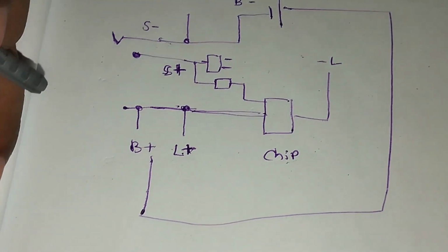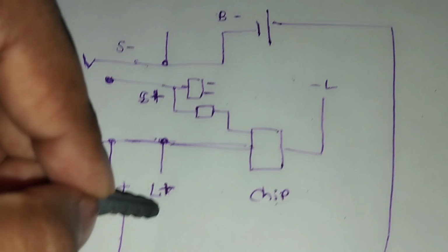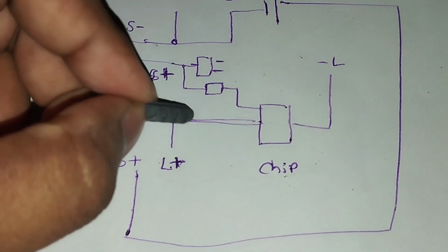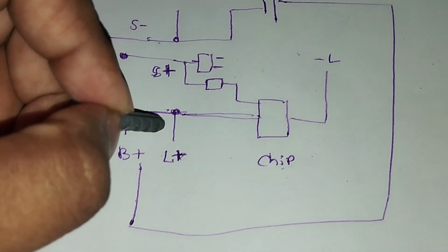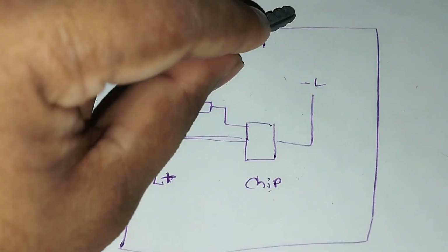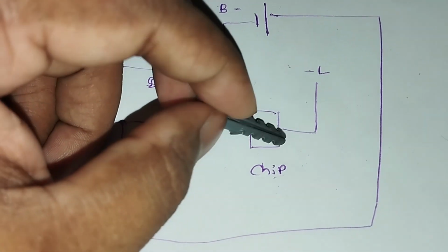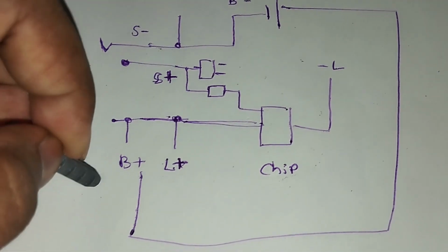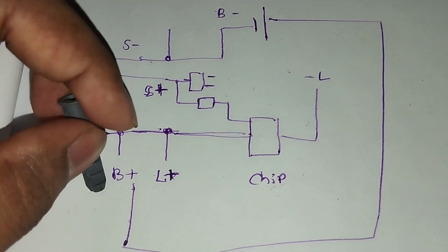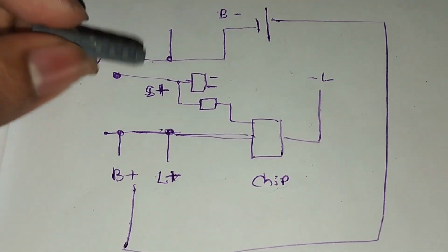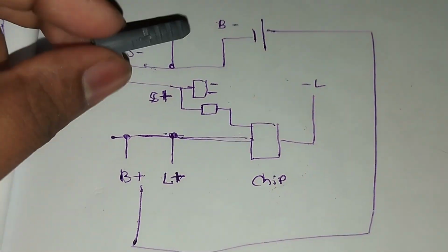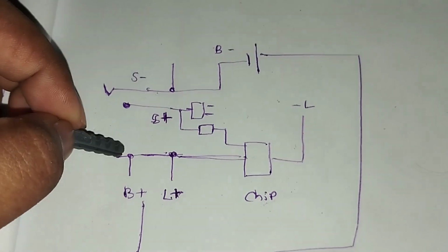Then they have supply negative also traced directly to the battery. That doesn't ensure your supply voltage is correct, or the correct polarity, or that plus and minus aren't mismatched. This plus goes straight to the transistor, but even if there is a misfire, it gets crazy, because that goes straight to the chip. I did not see any diodes or any other reverse polarity protection.